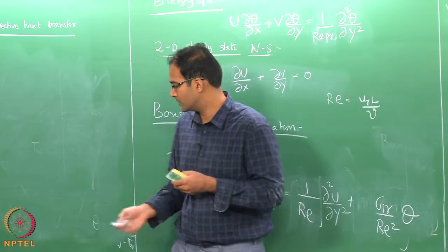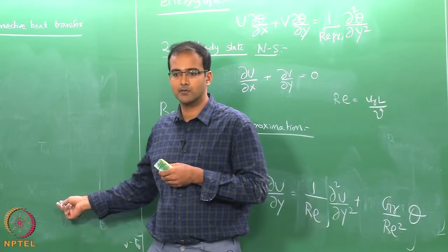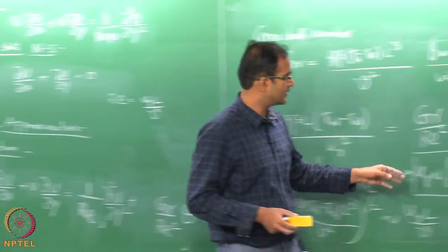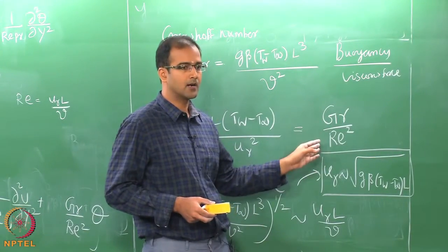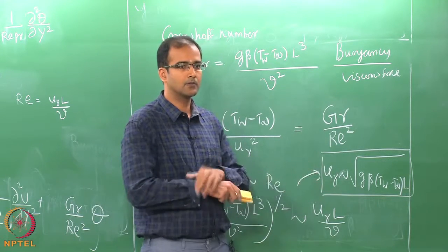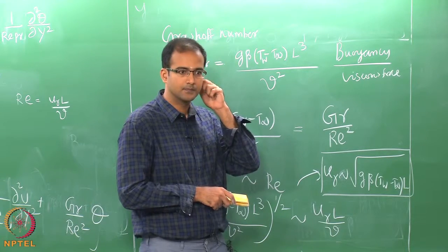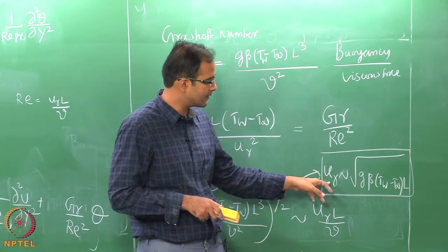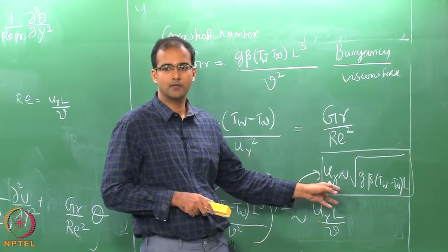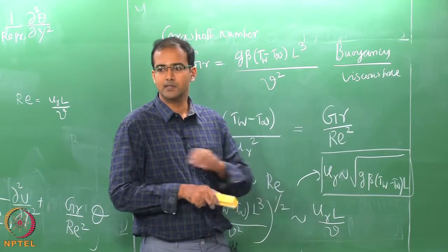Otherwise, when you non dimensionalize it, you do not know what your reference velocity is, but you can now, using the order of magnitude between Grashof and R e square, come to a reasonably good estimate of reference velocity. Okay. So, you can see that this reference velocity is nothing but what is going into your Reynolds number definition, and here it is driven by your temperature difference.